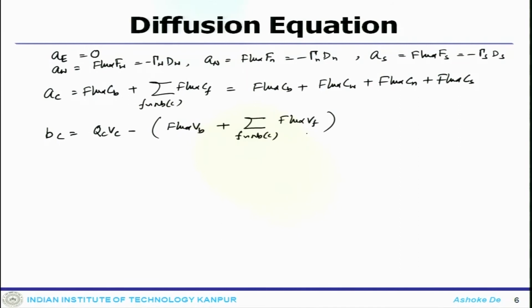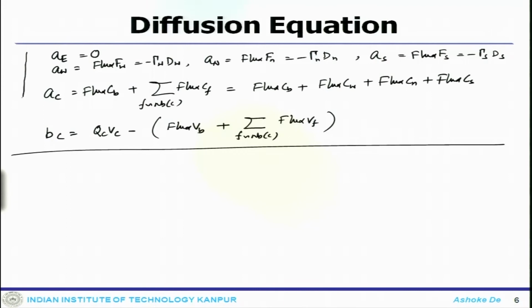Okay. So, though the discretized algebraic equation looks similar for all sorts of conditions like Dirichlet condition, Neumann condition and mixed condition, the differences lie in the expression of these coefficients and the source term. Now, these are the primary three boundary conditions which one can come across while applying boundary conditions for a physical problem. Either you have a specified value or you will have an applied flux.